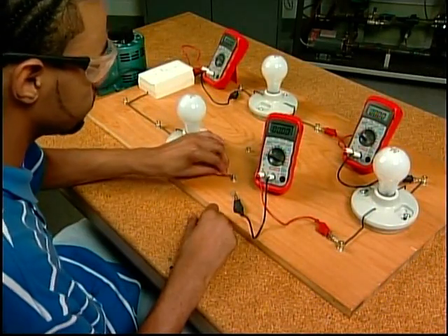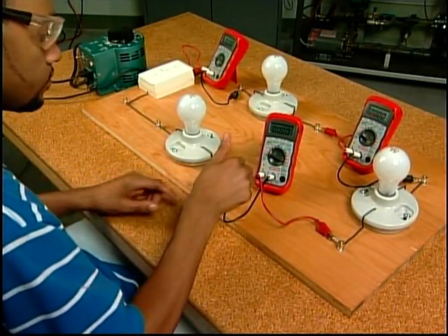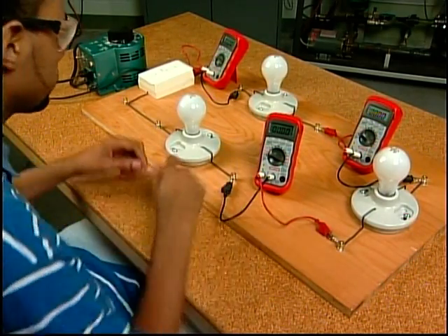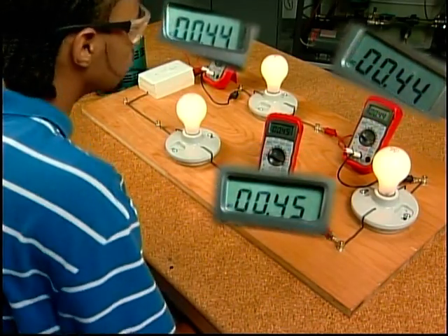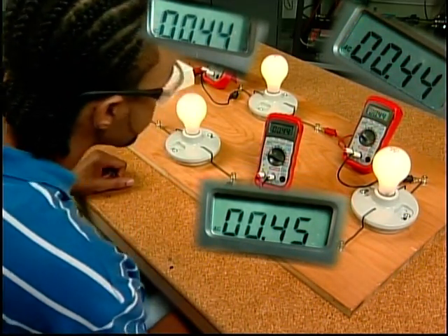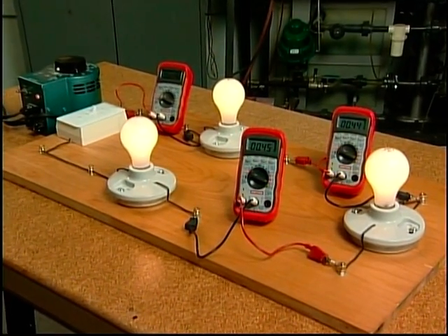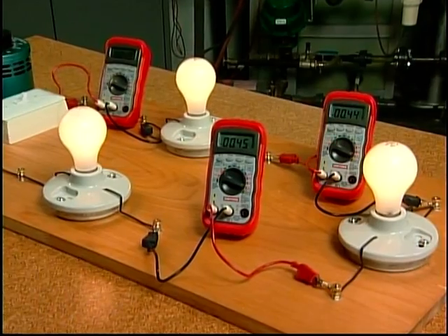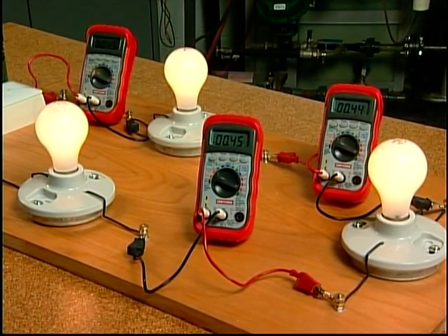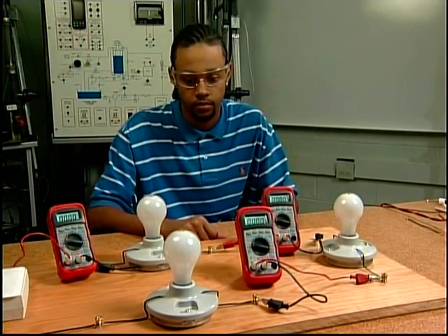To confirm these conclusions, rewire the circuit to have 3 equal loads of 100-watt lamps and 3 ammeters, and then close the switch. All ammeters indicate that there is 4/10 of an amp flowing in the circuit. There is less current flowing in the circuit with 3 lamps than there was with 2 lamps. Notice the decrease in brightness of the 3 lamps. This is due to the fact that each lamp is using less power. If any component in a series circuit fails, the whole circuit is affected.